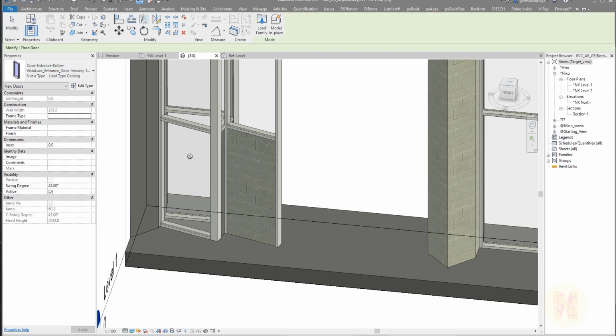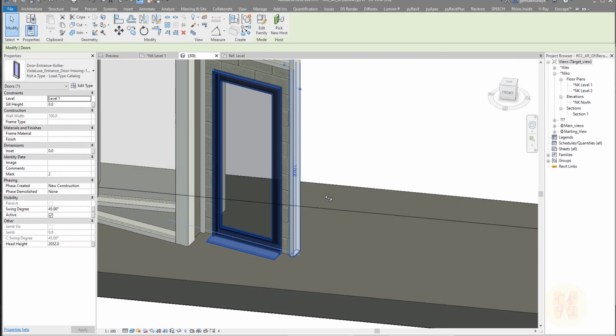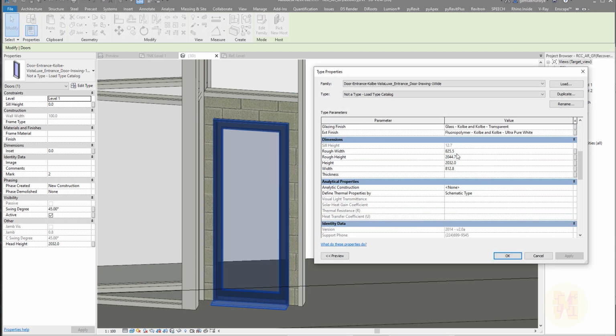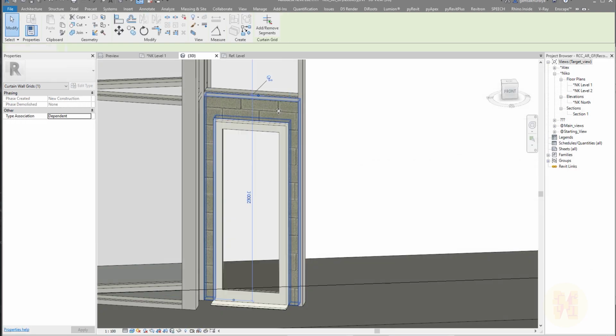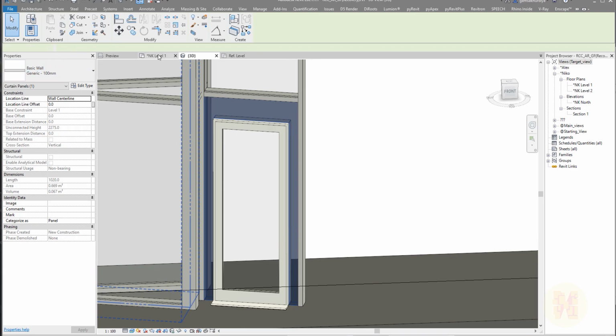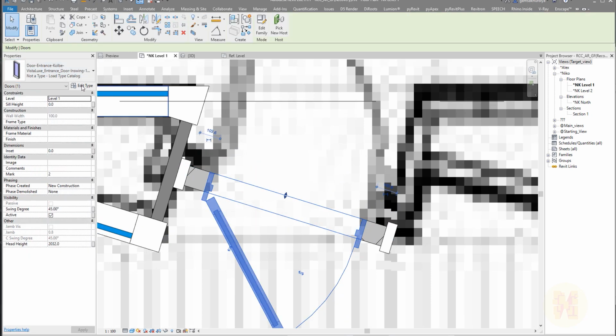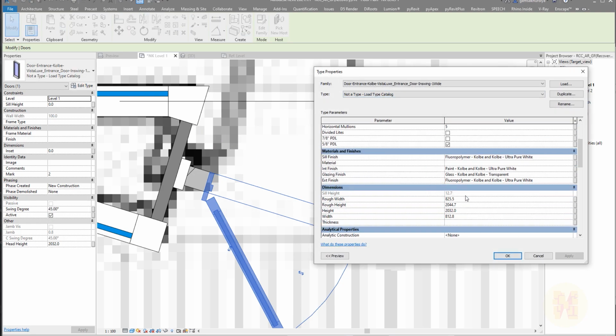Now we will go to the door. Here is my new door. I can place it already. I will place it, and I can change the dimension of this door. First of all, I can see it's exactly in the middle. Let me look at this door. It's again in inches, no. 800mm, my door. But I want to check this panel. We will not know how wide this panel is until we calculate it. This panel is 1020mm. So let me change this door and say this will be 1020mm. Let's apply it.